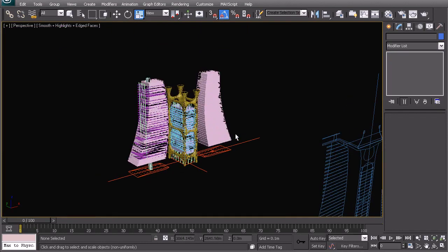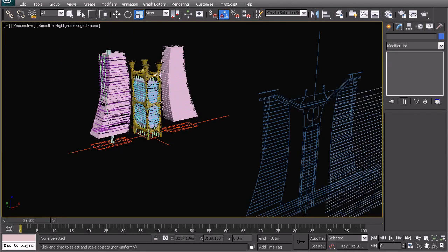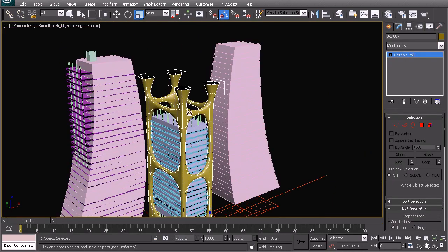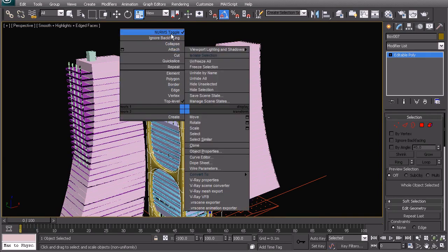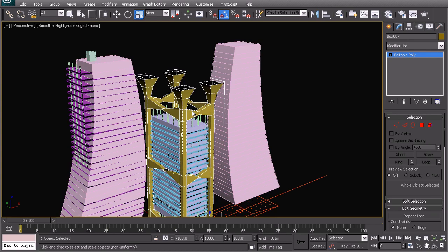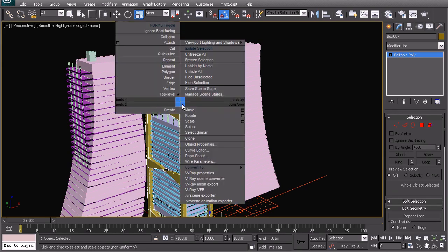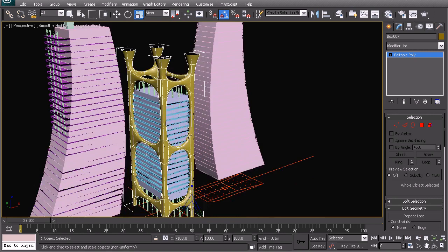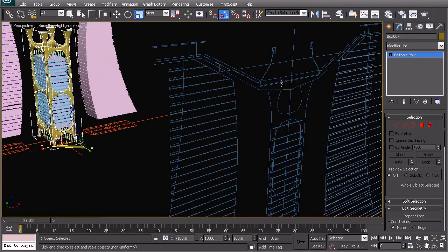Basically, in this video, we've made the one object, and we've gone through the process of how to start with a simple polygon, simple poly object, and how we applied the NURMS toggle through the right click. And then we learnt about the difference between setting up a shape using this object that we added the NURMS to versus creating a more complex shape out of many points or vertices or polys straight from the word go.